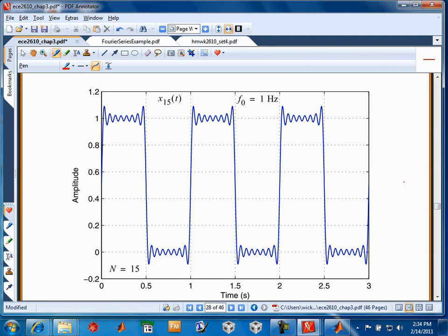It turns out that with the Fourier series representation of a waveform that has discontinuities in it, you cannot get absolute convergence everywhere. You can only get pointwise convergence. So the ideal square wave jumps back and forth. And it has problems trying to represent the discontinuity, and as a result of trying to handle that discontinuity, the jump that occurs from here up to here,